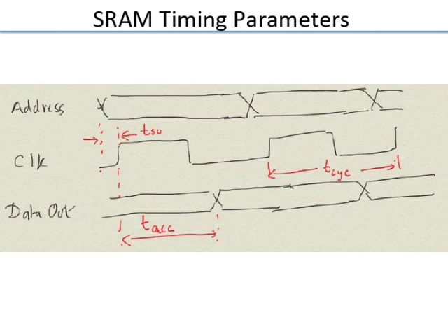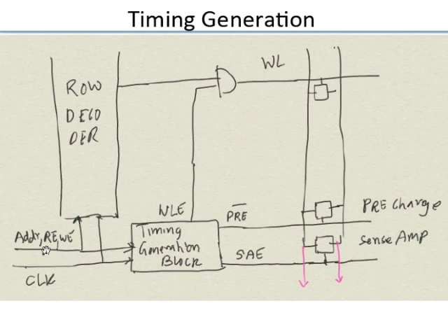But if you see in an SRAM, what happens? Let's go back to the figure. Here you have some number of address bits, and these address bits get decoded into one of many word lines. So where would you put in the pipe stage, and then you have the data coming out. Typically the time to decode and activate a word line, and the time from the word line going high to the data coming out, are roughly equal. Okay, 40, 60, there's a little bit of variation. So if you have to put a pipe stage, it has to be somewhere out here